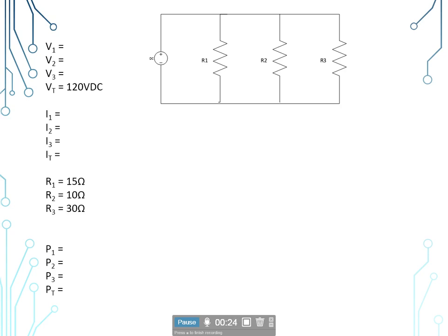So we'll be using a simple 3-branch parallel circuit. R sub 1 is the left, R sub 2 is the center, and R sub 3 is the right. We need to first trace our circuit, make sure we have more than one path for the current to flow. So here we go, we come to a node, we got a path here and a path here, another node, a path here and a path here, to this branch, all the way back to the node where they connect back together, there and there, and back full circle to our power source. So we do have 2 or more paths for the current to flow, so this is a parallel circuit.